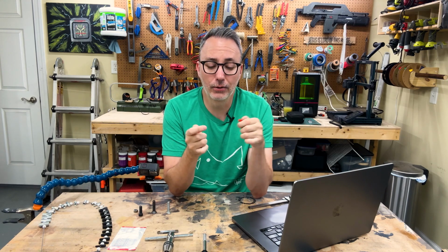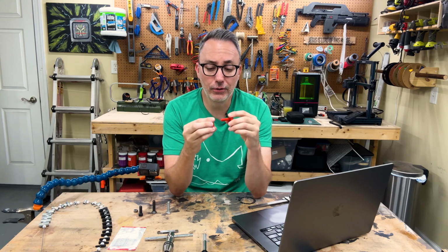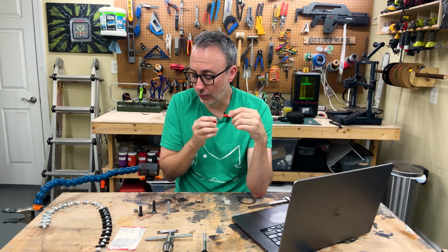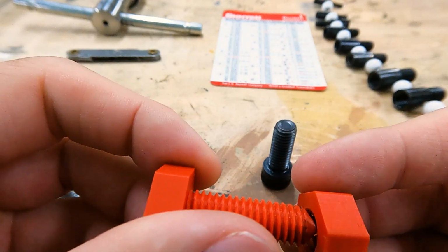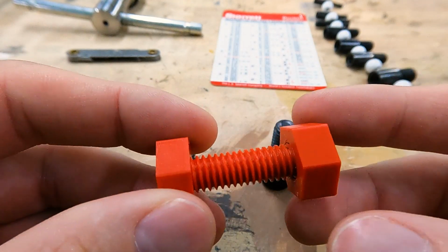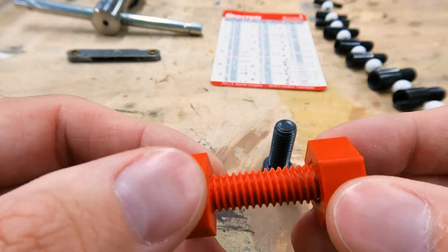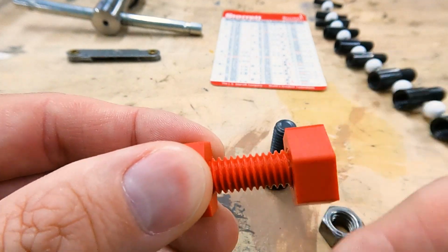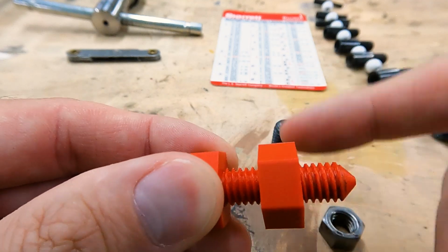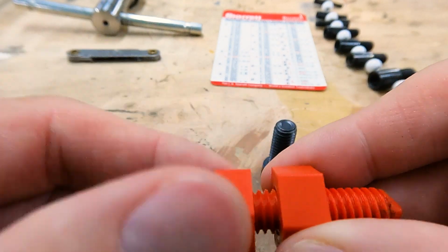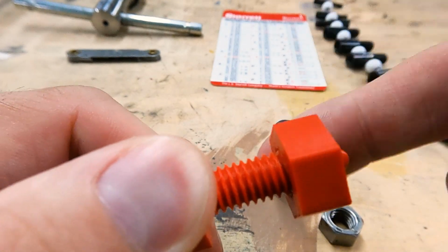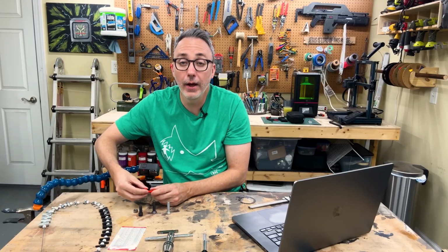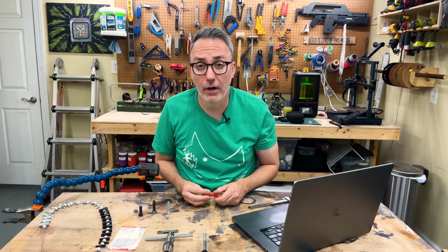You have to actually go in and model in a little bit of an offset to allow for the two pieces to screw together. So when I first made this nut and this bolt, they wouldn't actually screw on. So I had to add that offset to make them work. But now with the proper amount of offset, it screws on just perfectly. So when you're modeling, just know if you were to not add that offset, you're not going to get your parts to go together. But I'm going to show you how to offset.